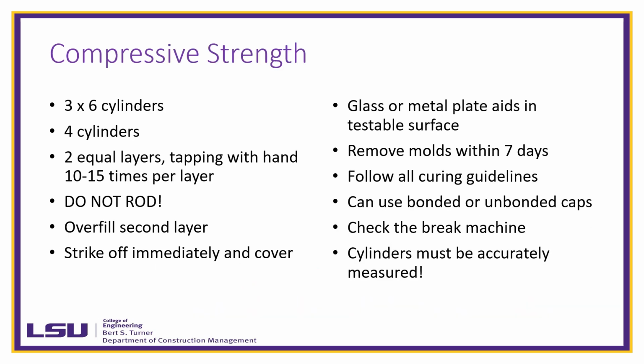Compressive strength. With cellular concrete, compressive strength is not necessarily the big driving factor. It is not necessarily structural in nature. It's just part of the entire system. So you're going to have very low compressive strength with cellular concrete.